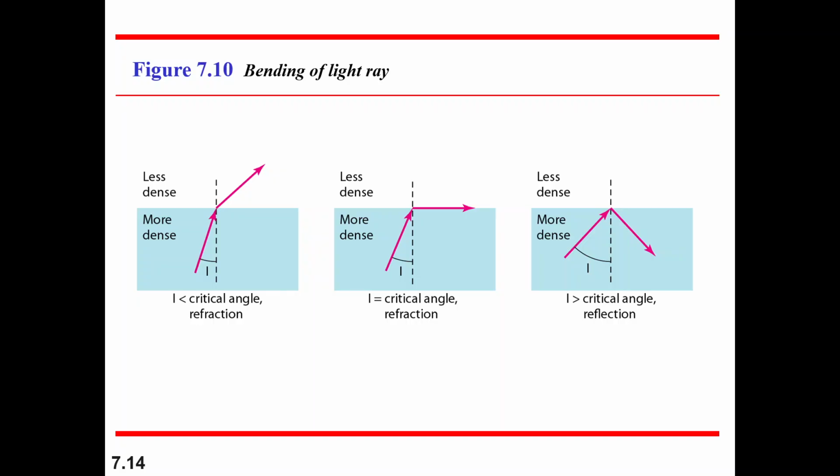Optical fibers use reflection to guide the light through a channel. A glass or plastic core is surrounded by a cladding of less dense glass or plastic. The difference in density of the two materials must be such that a beam of light moving through the core is reflected off the cladding instead of being refracted into it.